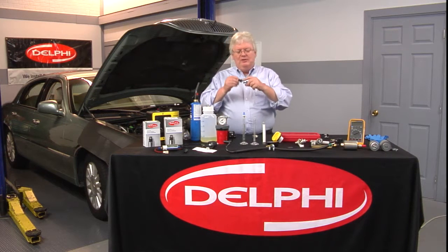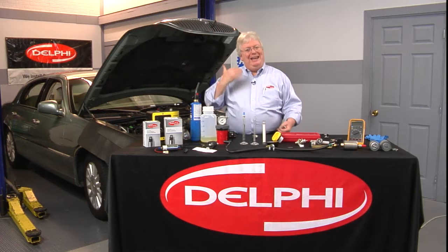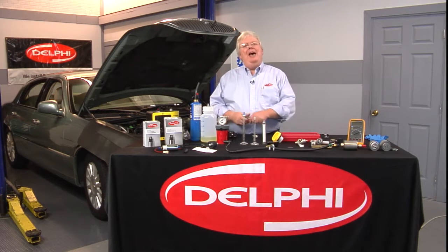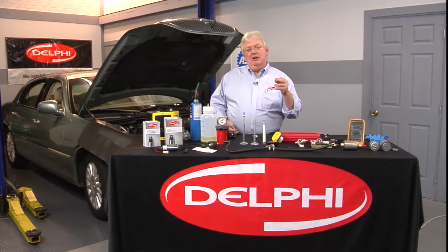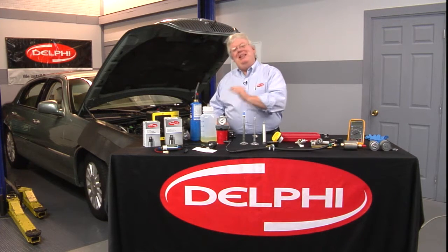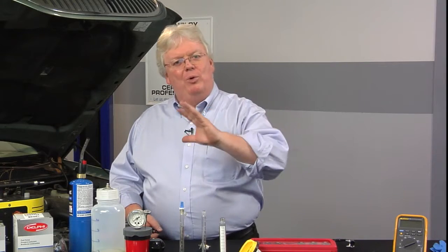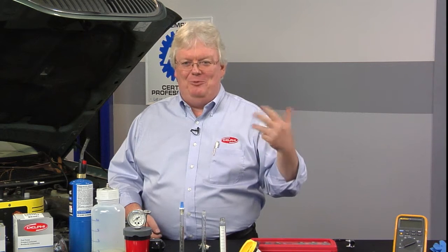It's also too much of a dilution, too much dosage of an aftermarket additive to a fuel system can cause fuel system damage, not only to the fuel pump, but to filters, elastomers, let's say the O-rings around the injectors, you name it, even the tank's plating if it's an older vehicle with a metal tank. So make sure your customers know, follow the directions on that additive, and certainly if they're going to err, err on the side of conservatism. Less cleaners, less additives, the better. Don't go overboard. It's like taking too much medicine. It can actually be worse than not taking your medicine at all.